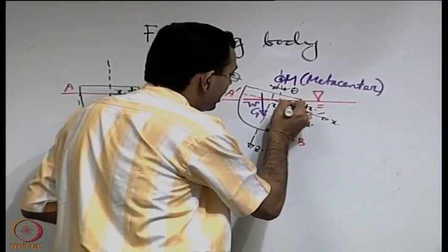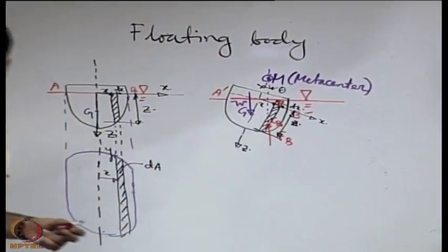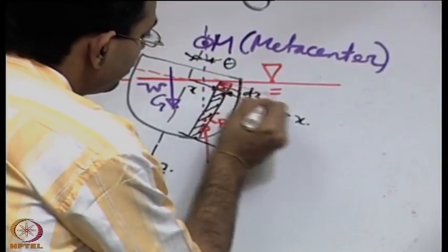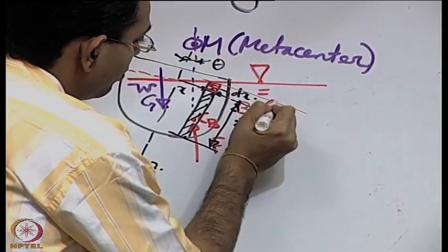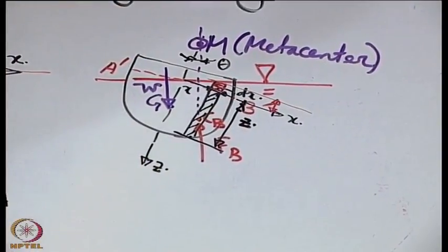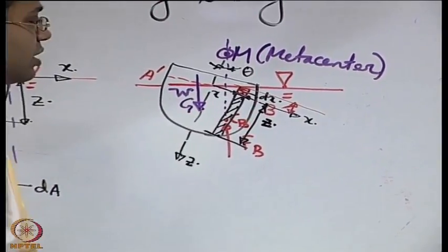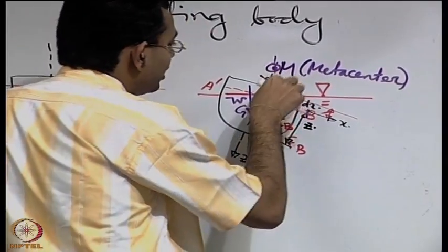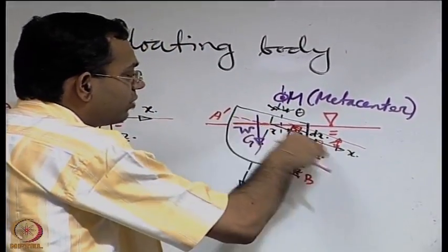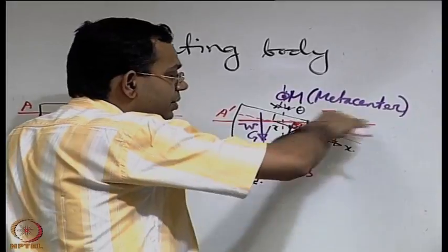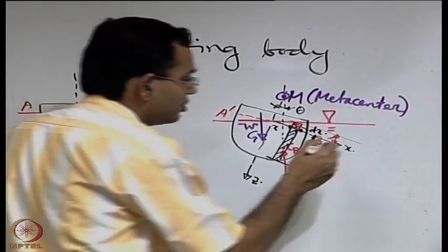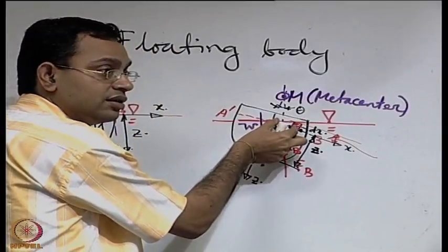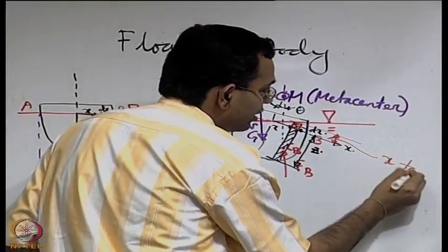So this is an additional displaced volume. This additional displaced part will correspond to a particular length along the z axis, and what is this? Remember that if this angle is theta, then the angle of tilt of the x axis with respect to the horizontal is also theta. So what is this dimension? You know that this is x, so that is x tan theta.